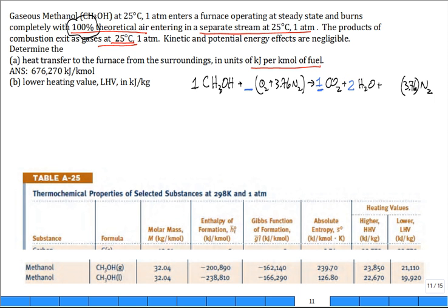So now let's balance the air. What coefficient goes out here? When in doubt, go slow. So we get 2 oxygen from here. We got 2 oxygen. I can add that in my head. That's 4. But I already have 1 oxygen from the fuel. So I need only 3 from here. 3 over 2. All right. So now we finish out with a 3 over 2 on the nitrogen.